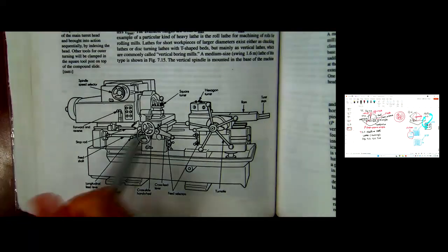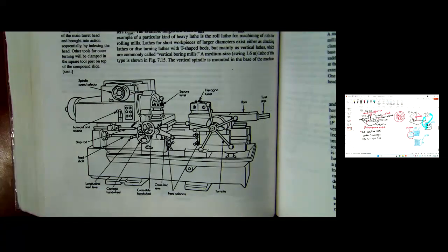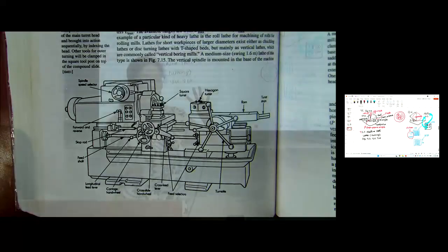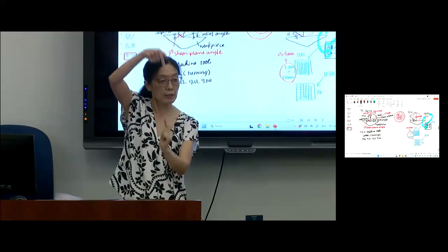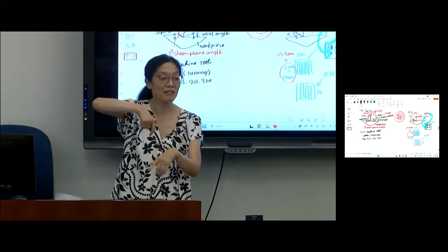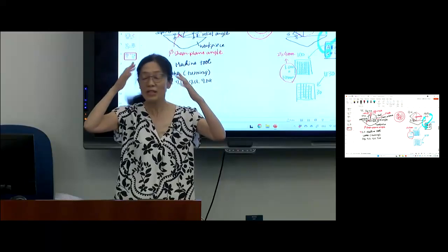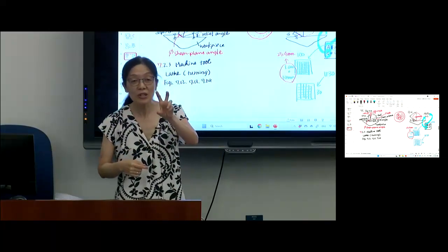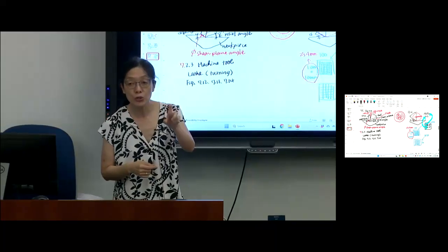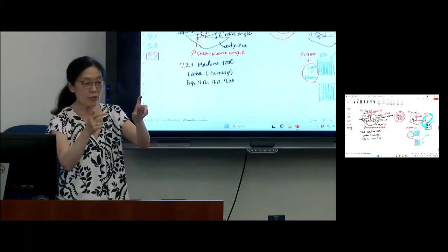And if I can add one more thing, it's the chuck. You have 3 jaw, right? Usually, but there are also 4 jaw chucks, right? So then you go like that. I'm not good at that. It takes forever for me. But for the 3 jaw, like I just mentioned, make sure to use a dial indicator.